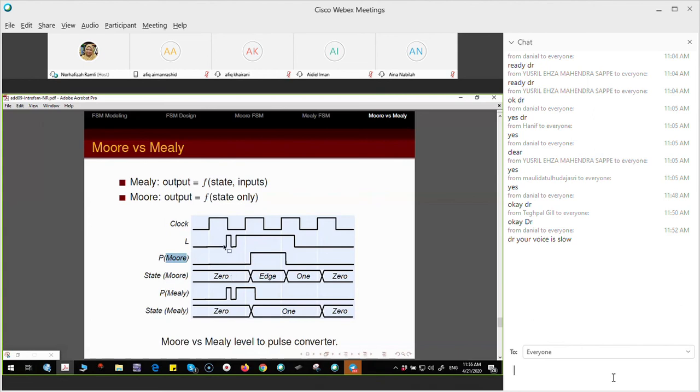And then this one is not recognized because it only recognizes at the clock time. So during the clock now, this is 1. So 1 means it goes to the edge because now it detects 0 and it detects 1. So the state goes to the second state. At the same time, the output is turned on. Now this delay is just the way of saying propagation delay. But when you do functional simulation, you don't see this delay. This delay is hardware-wise.